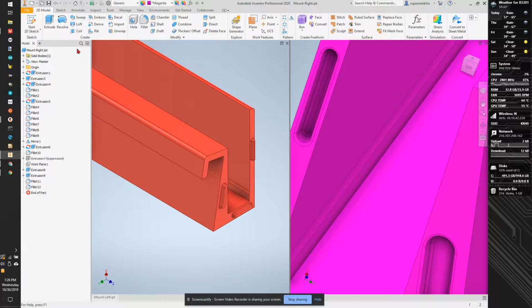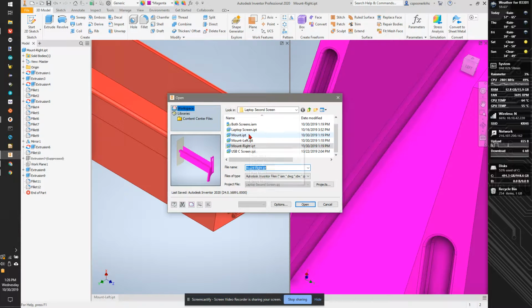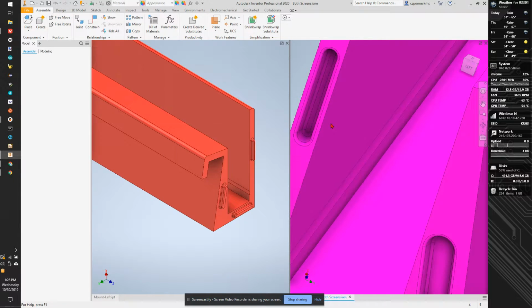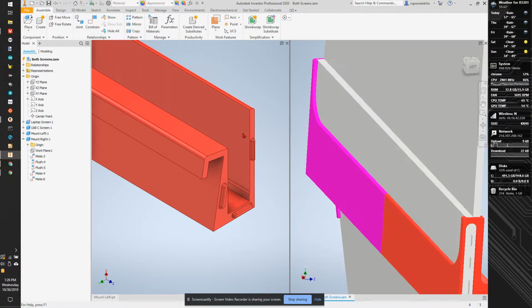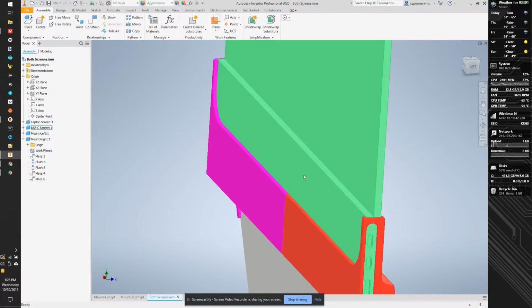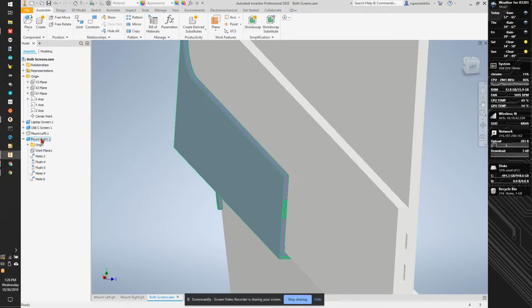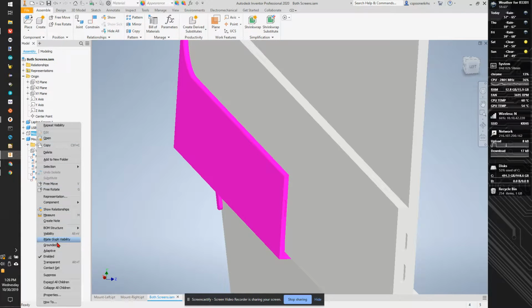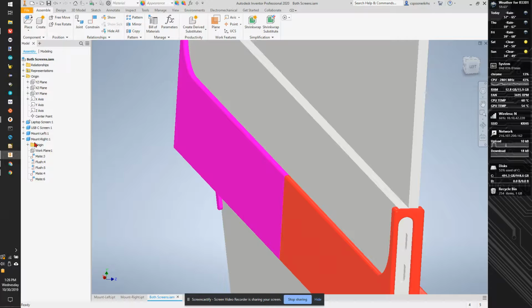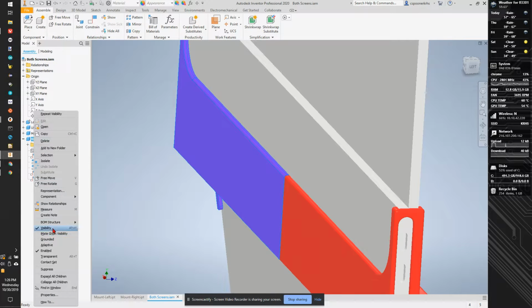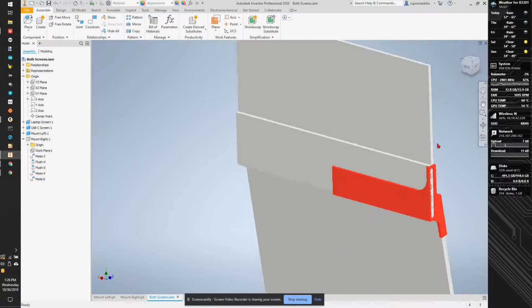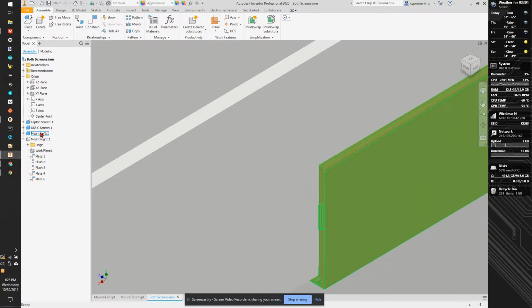Now we can go and reopen our assembly. And what we're going to do is do an interference test. So yes, we're going to update it. I'm going to make this full screen. I'm going to turn off visibility on one part just to see, we can see our female connections right there. I can do the same thing here, turn visibility off, and we should see the male connections if we flip around. Yep, we can see our male registration points.